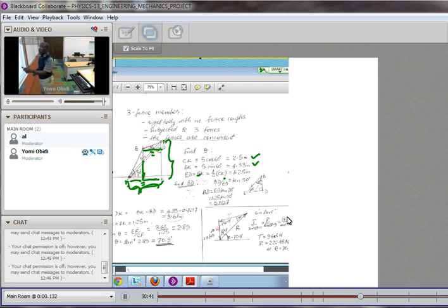Why is this useful? Well, the next thing we want to do is find BD. We know that BD over ED is the tangent of this angle, and this angle is 30 degrees. So we go on and find BD. BD is ED times tangent of 30 degrees, which is shown in a small separate diagram here.